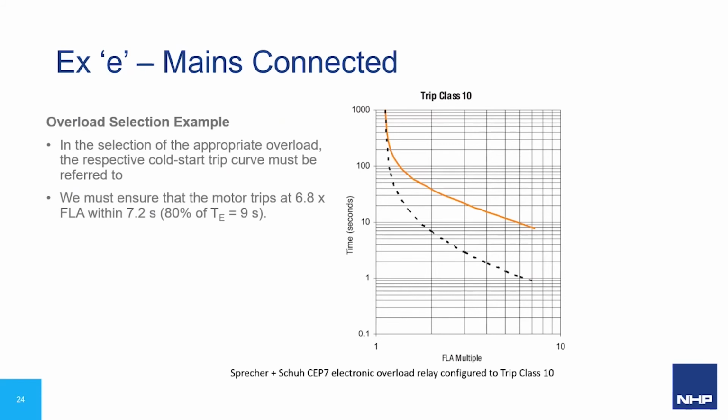So now we need to see if the trip point required by the EXE motor is above the cold trip curve, or the solid red line. And we need to look at this as this is the worst case condition where the motor is initially cool and hasn't been running for some time. And obviously it would run the longest within a locked rotor current condition before tripping.